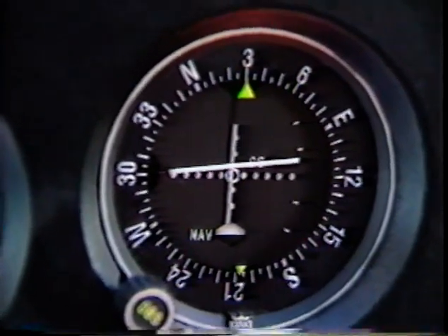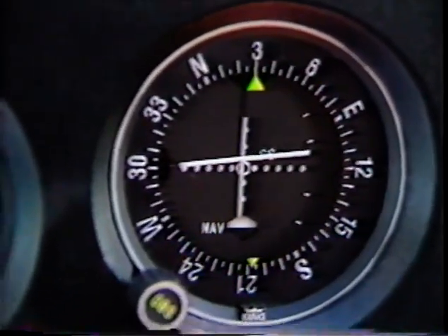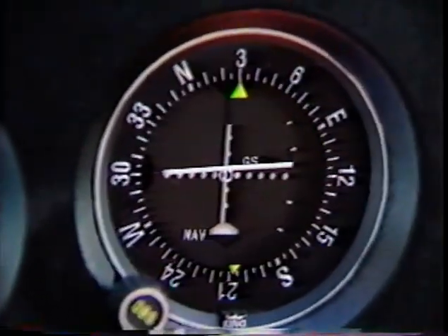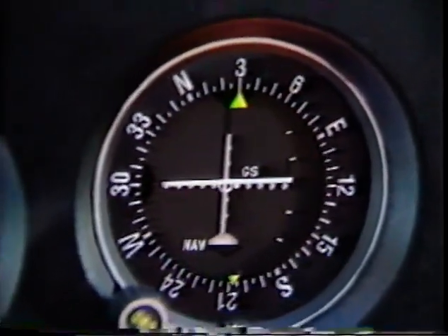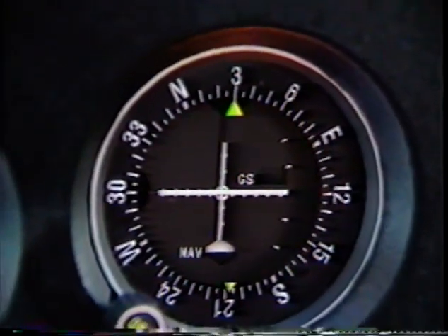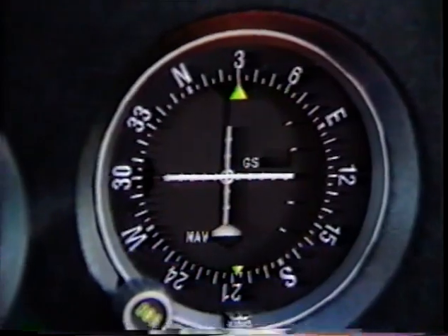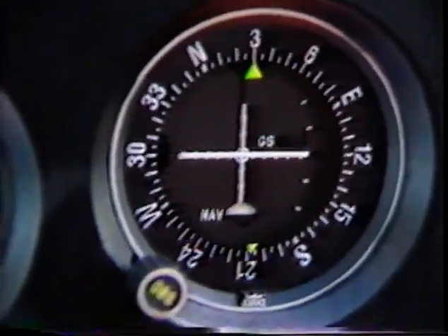On a day with a strong headwind, your reduced ground speed will require a smaller than normal rate of descent, a higher pitch attitude, and therefore a higher than normal power setting to maintain the desired indicated airspeed. Once the power has been set, glide path corrections are made with small pitch changes.